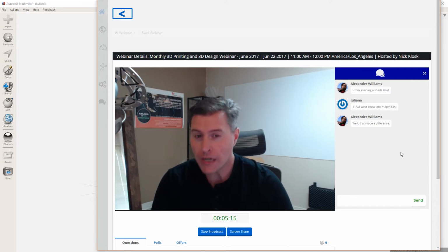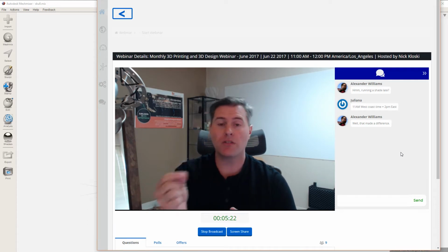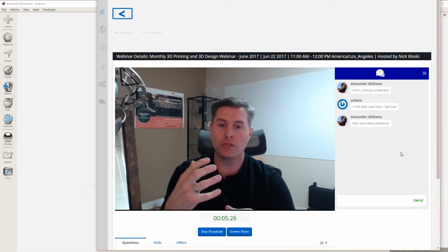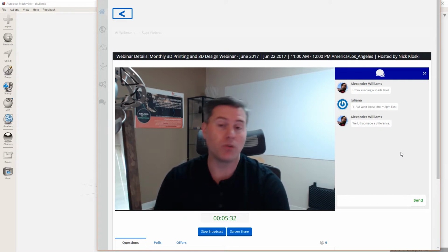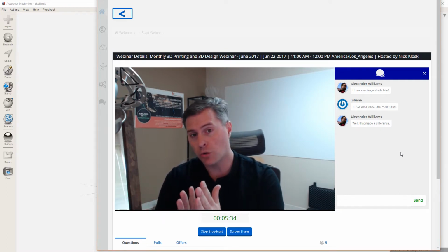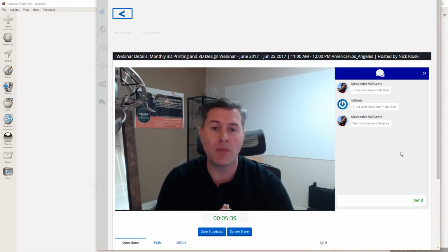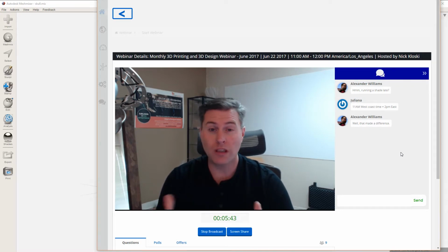And you can get pretty accurate with Meshmixer, but if you want to do things like creating very specific offsets from other things, you can do that, but the moment you touch them with other tools, you kind of get into the idea that Meshmixer is digital clay. You can be accurate with clay, you can smush it with different tools, but once you start doing other things, you can start to get less accurate. For some uses, like organic modeling and just working with scans and evaluating them, Meshmixer is awesome.